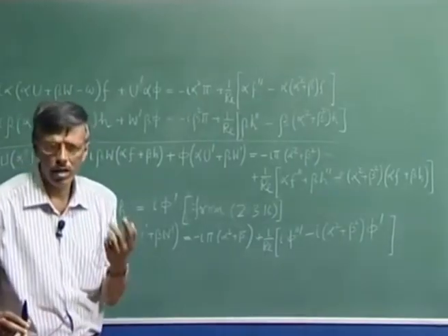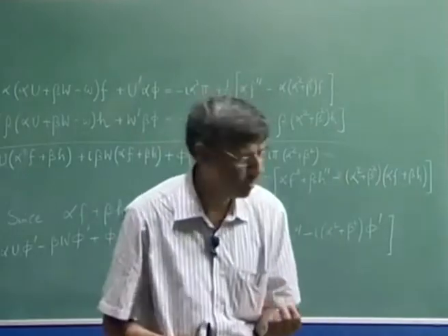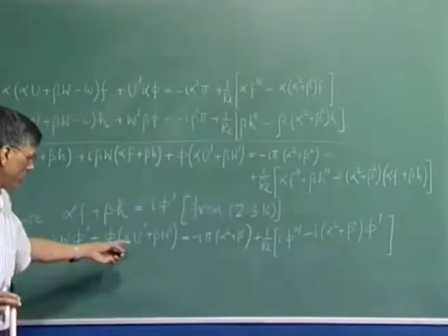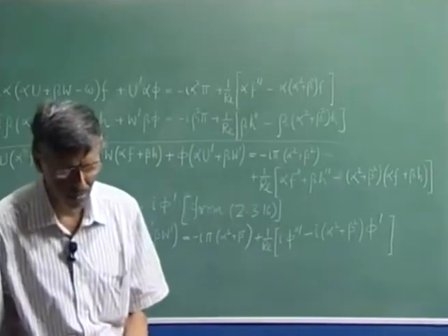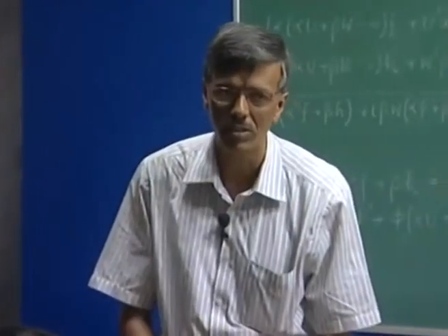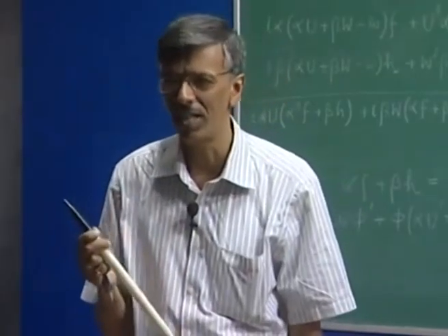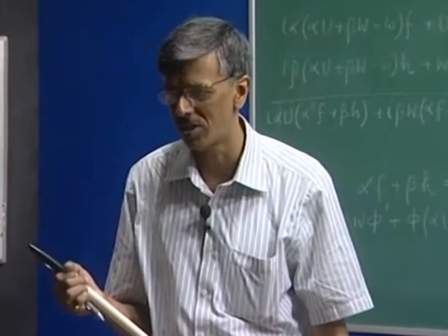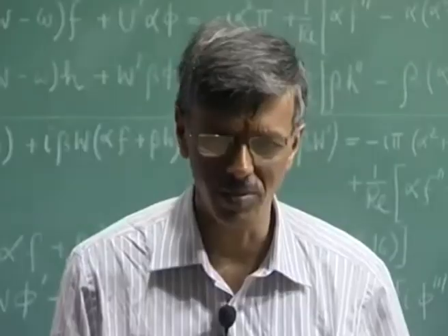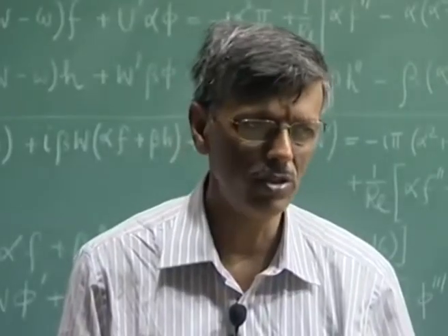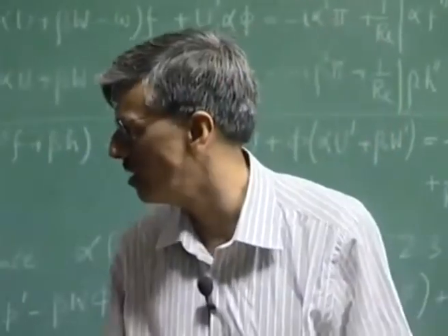even converted into a single equation, and that equation is a linear equation. The only problem is the coefficients are functions of y. So, this is basically a linear variable coefficients ordinary differential equation, and it is not easy to solve. I told you that using a desk calculator people could solve the Navier-Stokes equation in early 20th century, and the first good quality numerical solution emerged only beyond 1950. So, it's not a very trivial exercise.